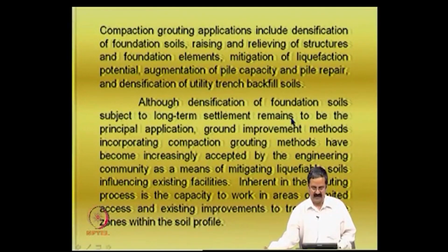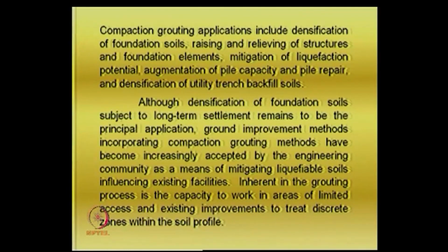Although densification of foundation soils subject to long settlement remains the principal application, ground improvement methods incorporating compaction grouting methods have become increasingly accepted by the engineering community as a means of mitigating liquefiable soils influencing existing facilities. As I just mentioned, since you have excellent equipment and quality control, like machine control, the possibility is that yes, this method can give good improvements.